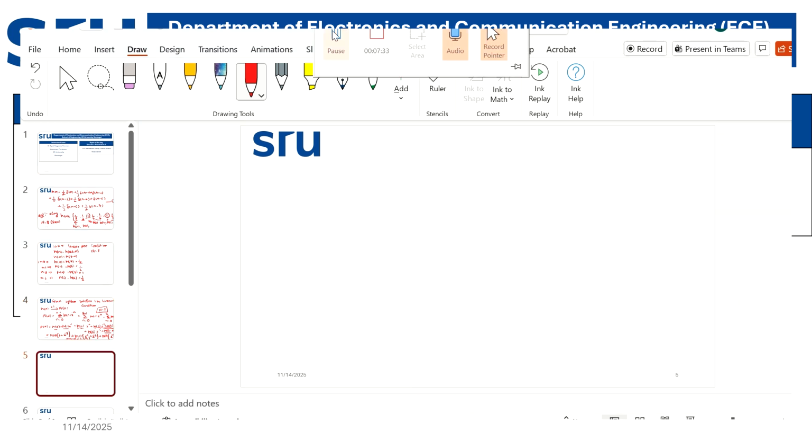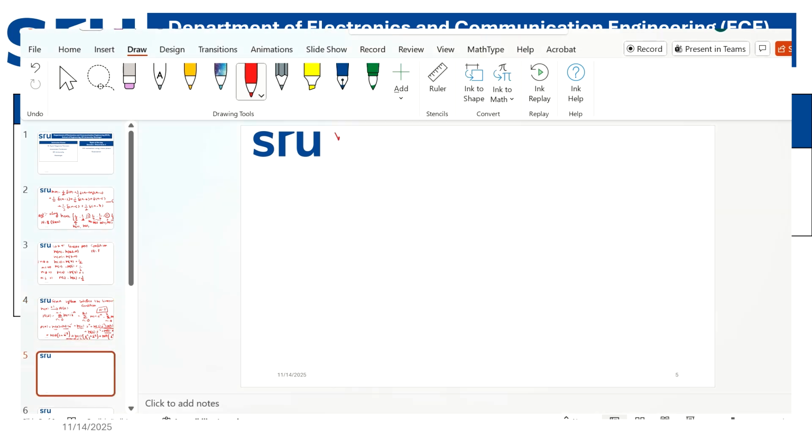Now if I substitute all the h of 0 coefficients: h of 0 is equal to 1 by 2, h of 1 is equal to 1 by 3, h of 2 is equal to 1, and h of 3 is equal to 1 by 4. Therefore H of Z, that is the transfer function, I can write as output Z transformation by input Z transformation.